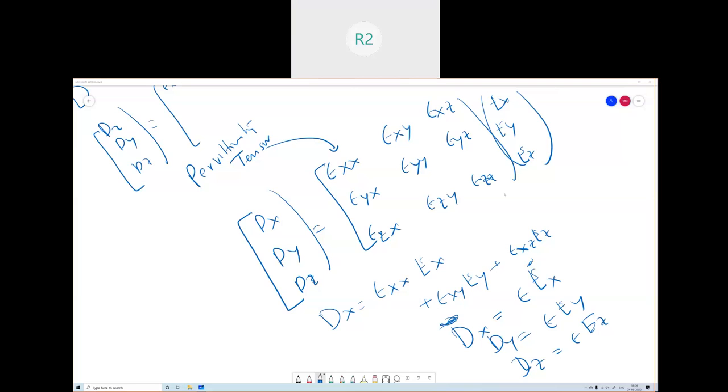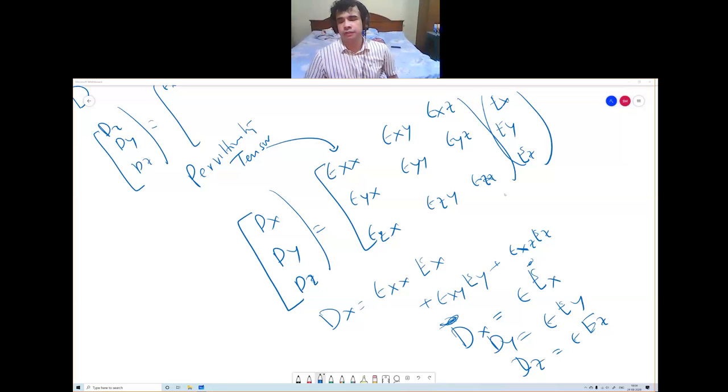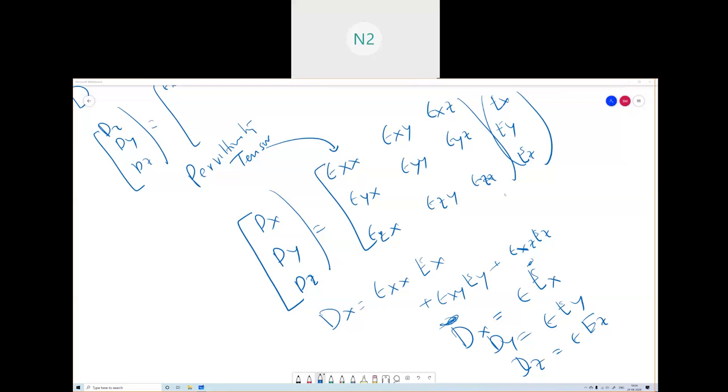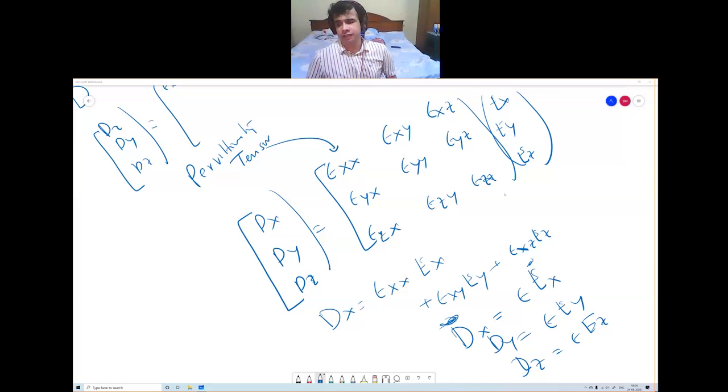Sir, can you repeat the non-dispersive part? Non-dispersive means that epsilon, mu, and sigma are independent of frequency. Had they been dispersive, they would have been functions of frequency. But we assume it's non-dispersive. We can simply write D equal to epsilon E, independent of frequency. Okay. This linear, homogeneous, and isotropic assumption is very commonly used. We assume it is isotropic and linear for this course.